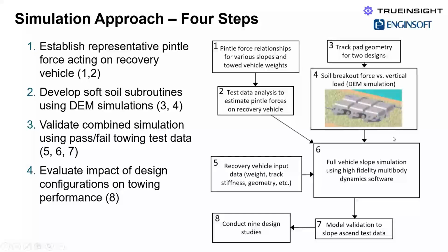So what we did is we came up with a virtual test bin, and we loaded it up with particles, and we'll show animations of this in a few slides. We applied a normal force to push down on basically 3 track links, or track shoes, together.